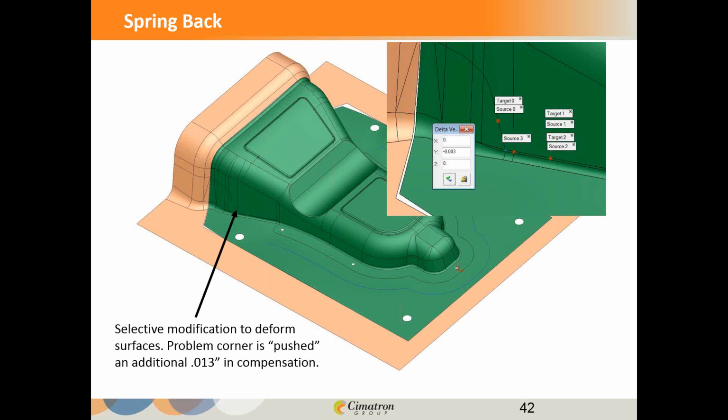But right about where that particular point is, right here, source 3, that would be the point where I'd push it in 13. And I would also work my way up and down along that edge so that I can control how much it's moving. So it doesn't drastically go from 0 to 13 and give me any sort of squiggle, I'm controlling it, smoothly changing those values. That's why I put in a lot more control points. You see 3 more control points in red. In real practice, I would probably put in more so that I can get that nice smooth edge like I like. Okay.